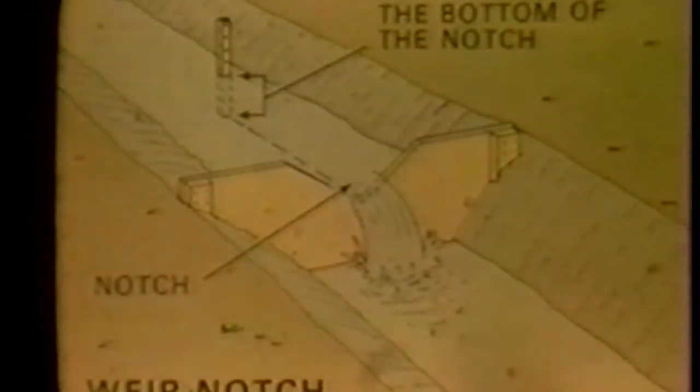Another method is the use of a weir notch, which is a more accurate measurement of stream flow. The quantity or volume of water flow is determined by first making measurements of depth of flow through the device and comparing these measurements to a table of values prepared for that service. A third method is the partial flume, which measures the depth of the water at 2 points in the flume by gauges. Then the quantity of water flow is determined from a table of values prepared for that particular flume. Your area engineer can help you with the procedures and tables for either of these methods.